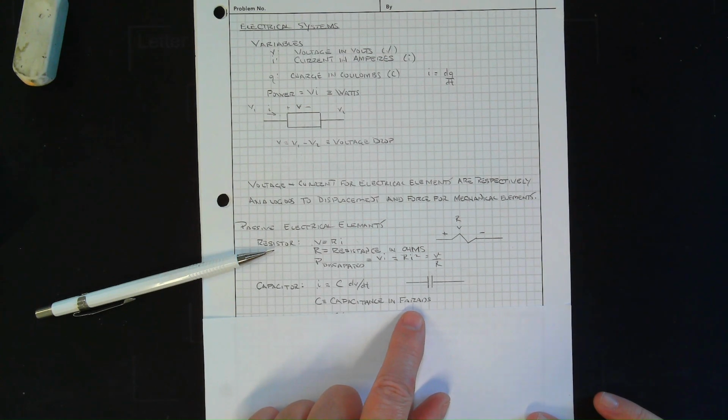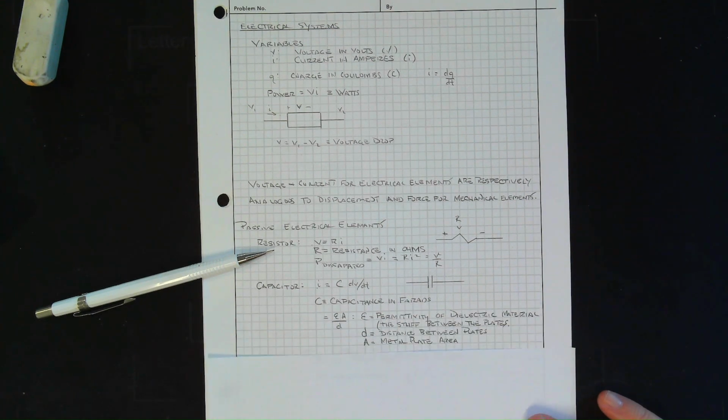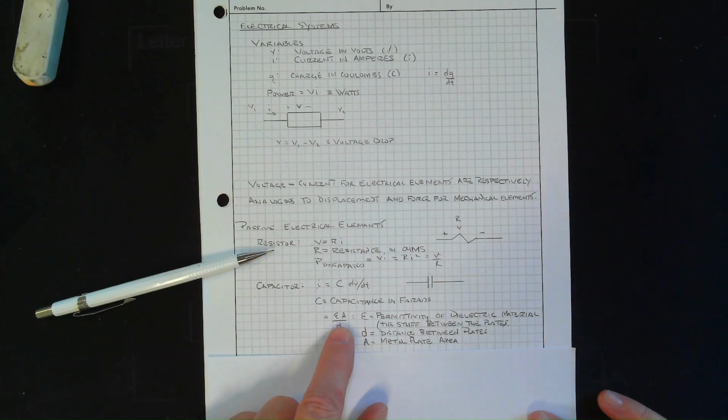Okay, a farad's a pretty serious unit. If you have something that's a farad size capacitor, and it's been fully charged, and you put your fingers across the conductors, it's going to hurt. So that's why if you handle a capacitor, you want to make sure that it has been discharged, because you can get quite a little shock from them and burn.